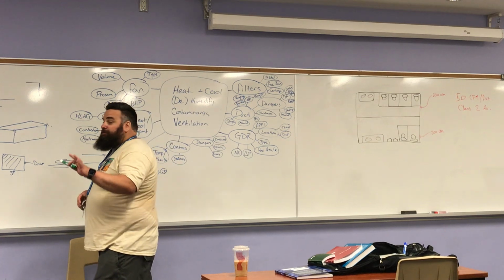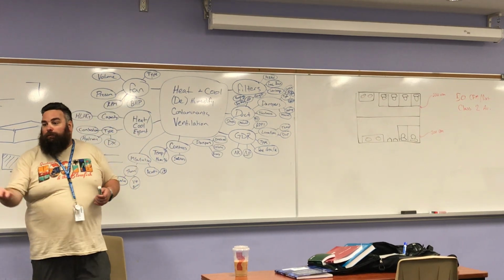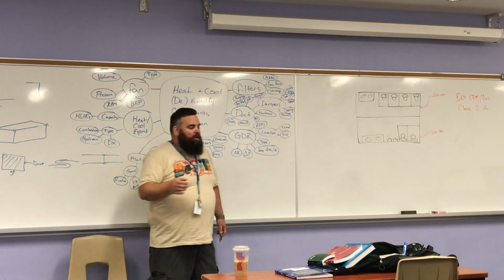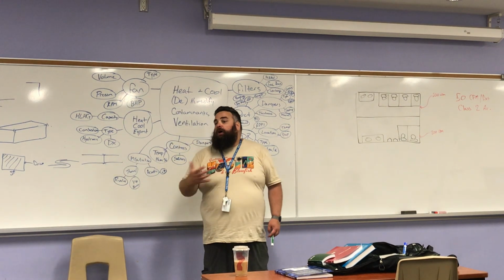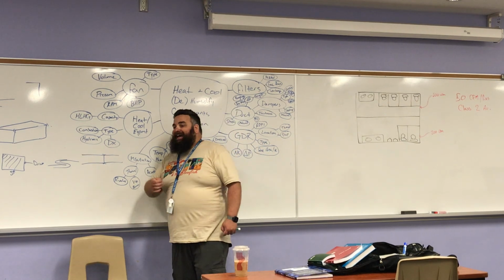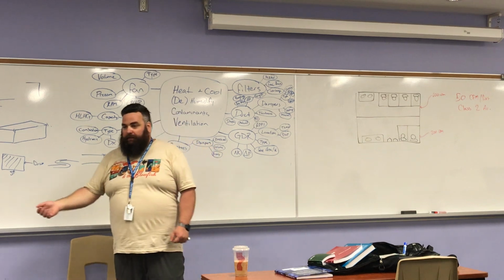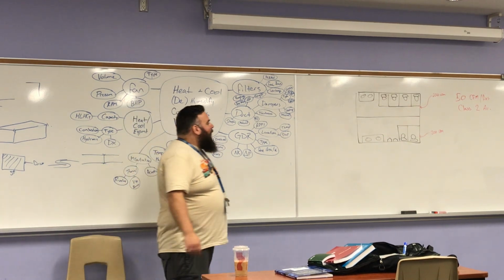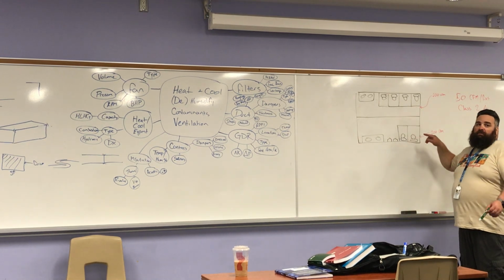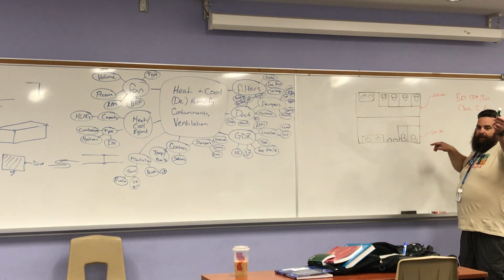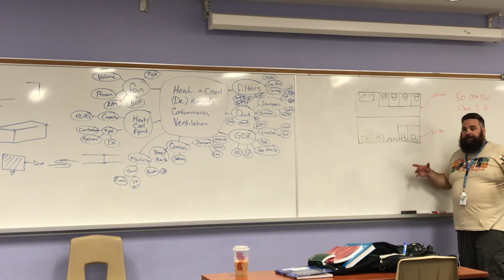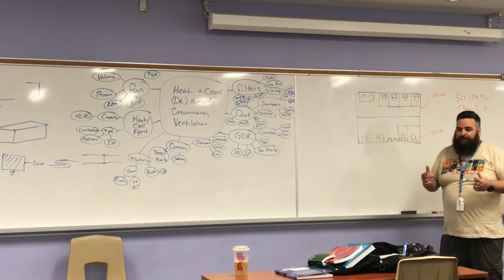And this is something that comes with experience. I don't expect you to know this now, but we'll talk about it. And that's the economics of this stuff, okay? Everything has cost. My job is spending other people's money, but to spend it reasonably. Can I justify the cost and complexity of a design? I can justify putting, like, let's say that egg crate, we call it, that return air grill. I can justify putting a lot more of those in than I can put in a linear bar grill. Linear bar grills are really expensive.